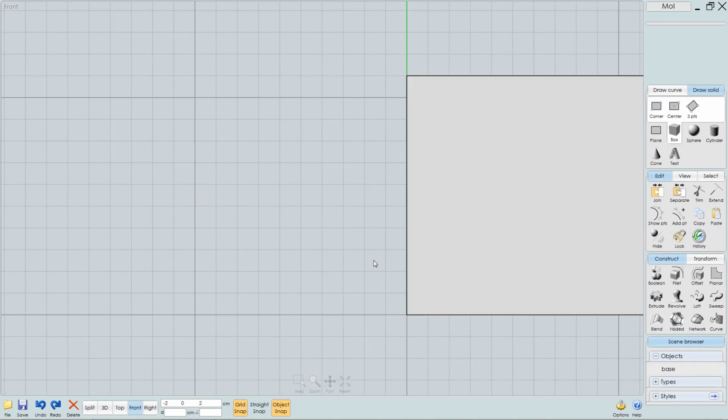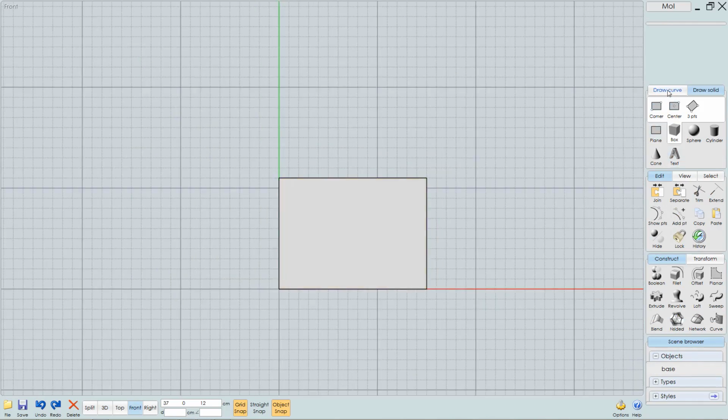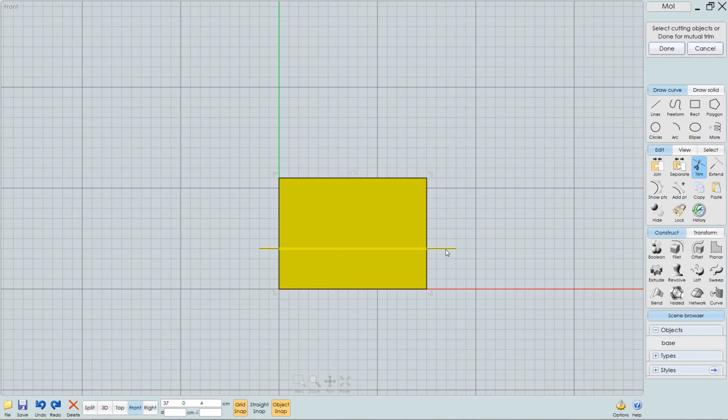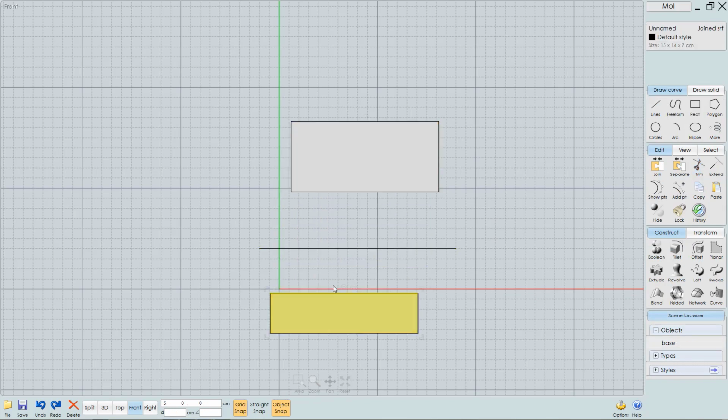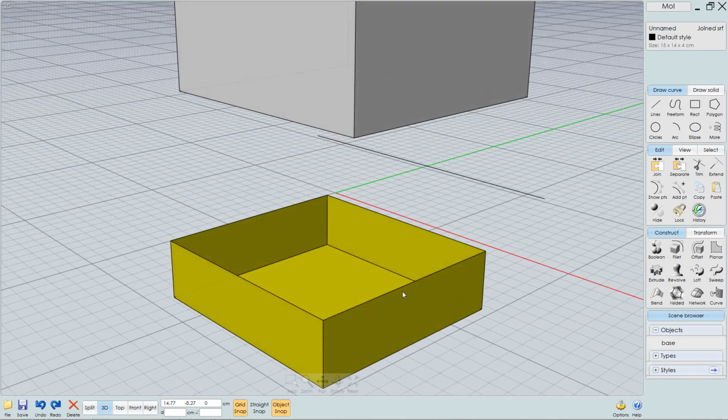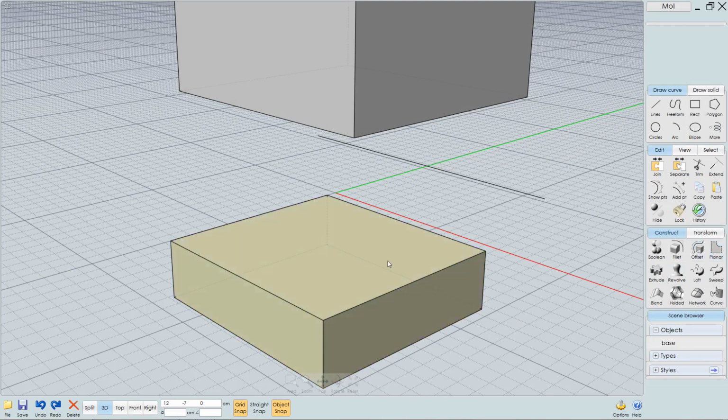And I'll create another curve, and this time I'm just going to draw a straight line. And I'll select the cube and again trim the object, select the cutting object, confirm twice, so we get these 3 objects which are hollow. And because it's a straight surface, I can now just select this object and use planar under construct to close that opening.